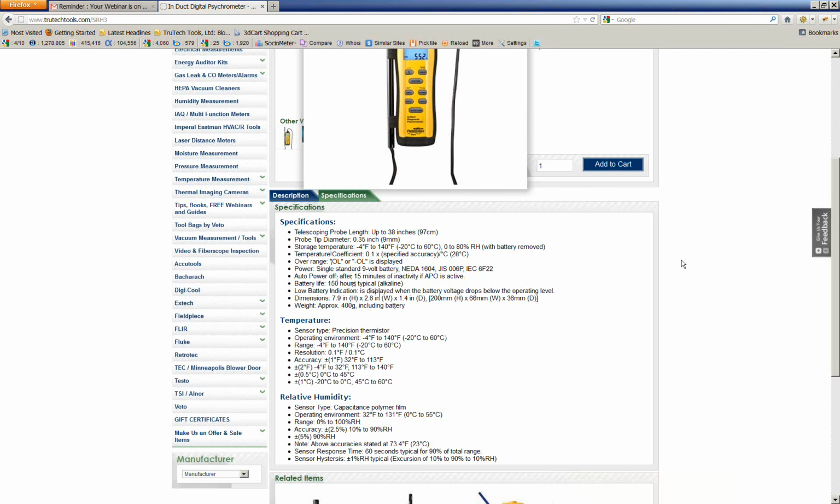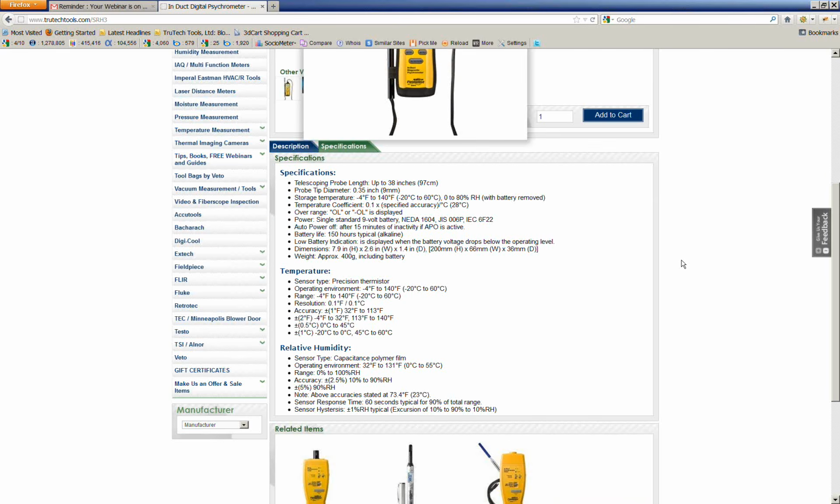Any other questions, Bill? Yeah, one more. 3 to 4 feet is not always possible, especially on second-story houses or ducts encased in chases. You've got to get as close as you can. There are some systems that just aren't conducive to testing, and I've seen those. In Ohio here we get a lot of slab homes, and it's really hard to get under the coil into the slab. It's impossible. So what you've got to do is go to the closest register you can to make your return and supply measurements, and that's about the best you're going to do at that point. So sometimes that really bites.